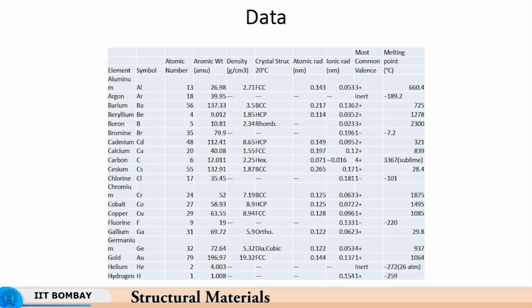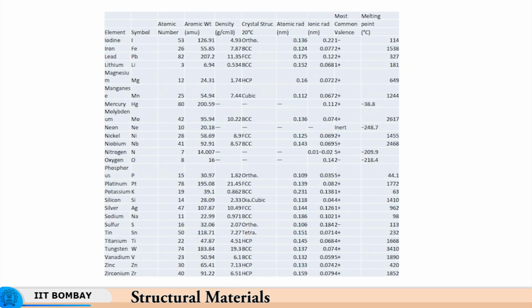You have an ionic radius of 0.053 and oxygen has got 0.14. So the center to center separation, if the two ions were touching each other, would be roughly 0.19 nanometers. So basically one can calculate the minimum center to center separation between these two ions for one positive ion and another negative ion.